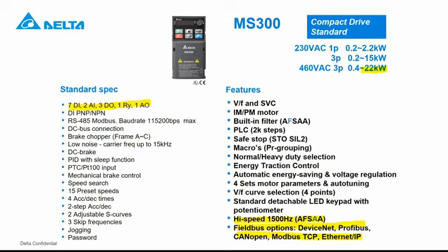So, of course, if you are running a motor at up to 1,500 hertz, then it's good to remember to set a carrier frequency which is at least 15 kilohertz. And when you do set a drive to 15 kilohertz, then it's also good to remember that there is some derating required, and we'll go through that a bit later in the presentation.